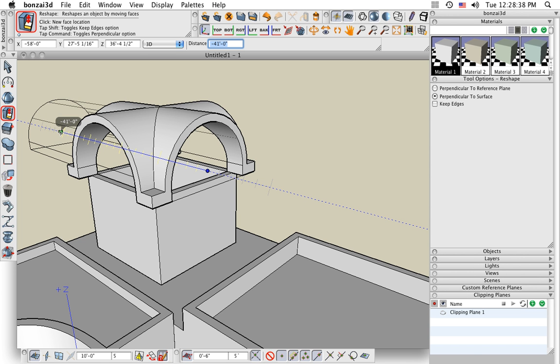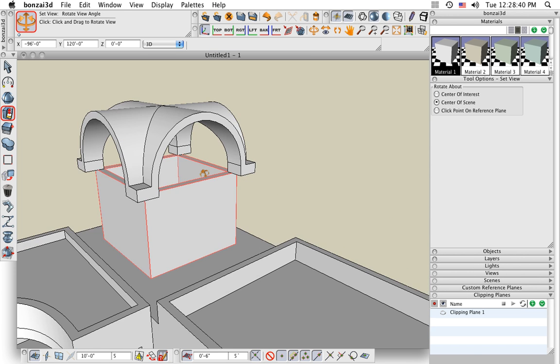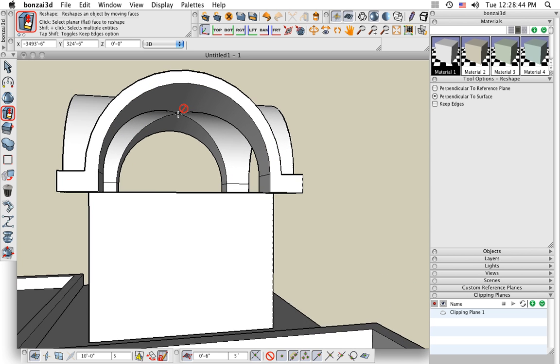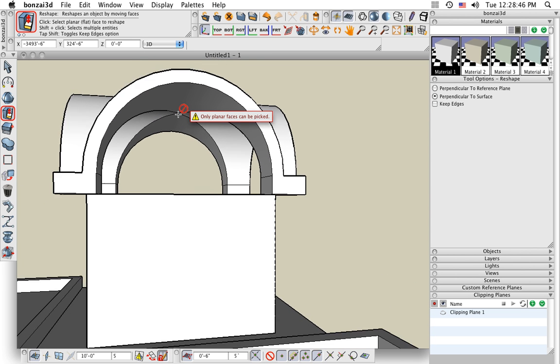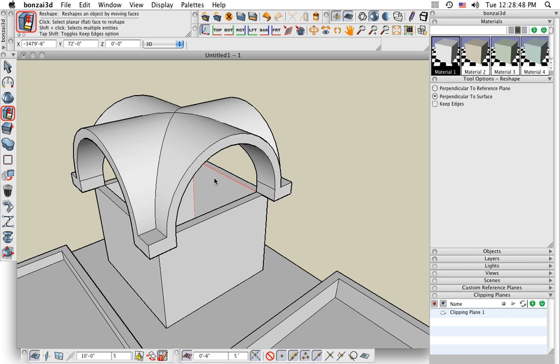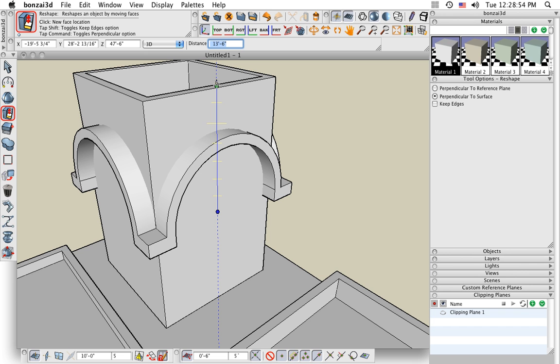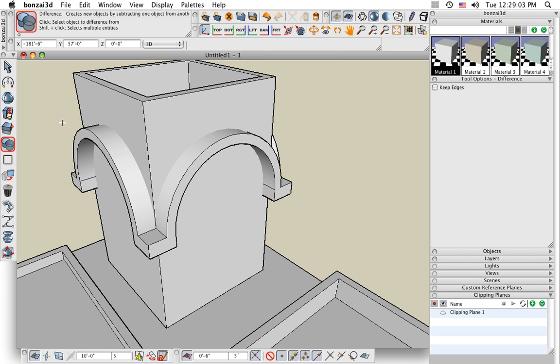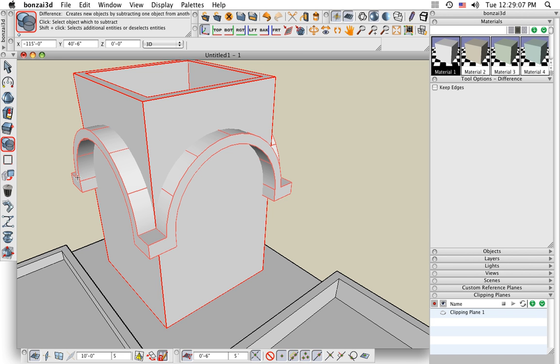And these are Boolean operations that are happening here interactively. You can see that it creates the proper intersection and vault structure here for us. While we're at it, let's also extend that wall up to the underside of that new structure. So first I'll just extend it all the way through temporarily. And then use the Boolean operations one more time by subtracting one shape from the other. So I can take the wall and subtract the roof from it.